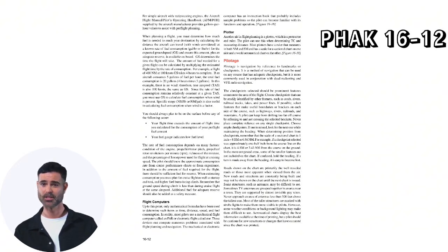Pilotage is navigation by reference to landmarks or checkpoints. It is a method of navigation that can be used on any course that has adequate checkpoints, but it is more commonly used in conjunction with dead reckoning and VFR radio navigation. The checkpoints selected should be prominent features common to the area of the flight. Choose checkpoints that can be readily identified by other features, such as roads, rivers, railroad tracks, lakes, and power lines.